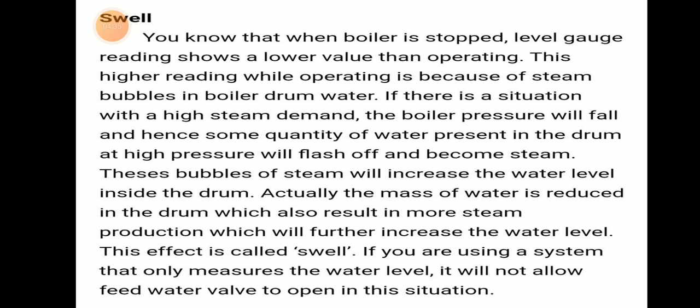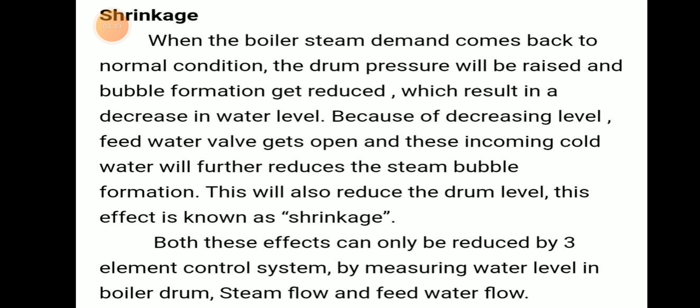If you are using a system that only measures the water level, it will not open the feed water valve to allow more water and reduce the steam production. This kind of situation is known as swelling.